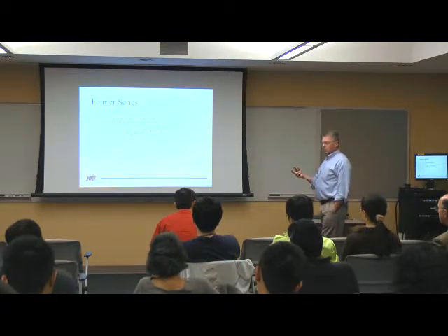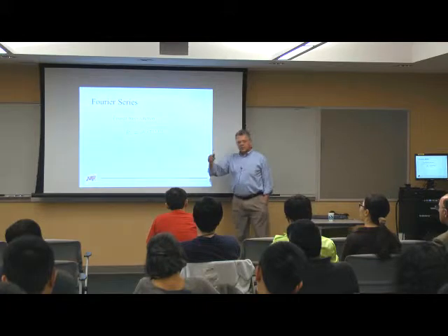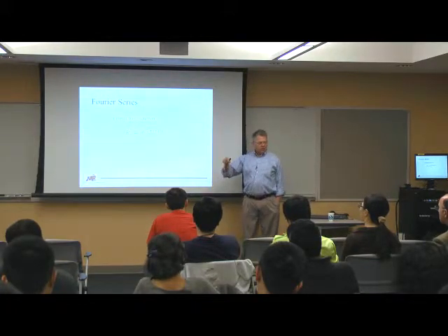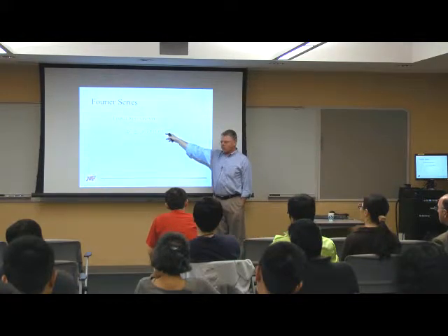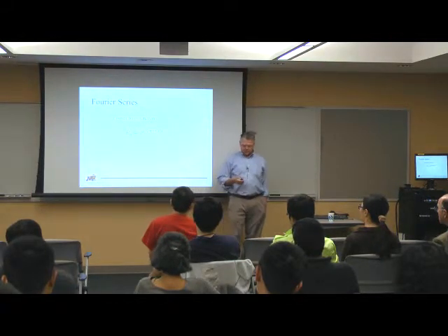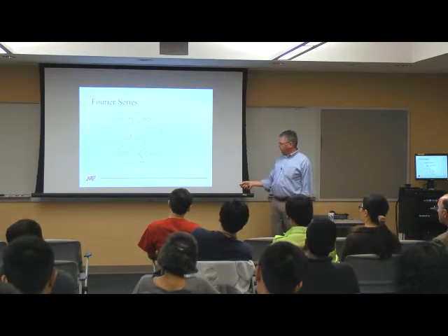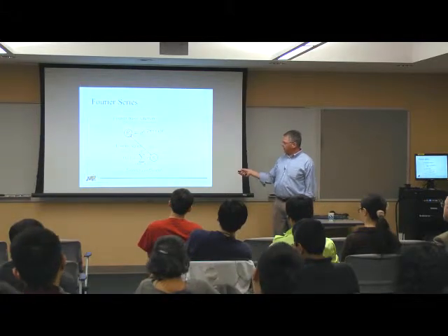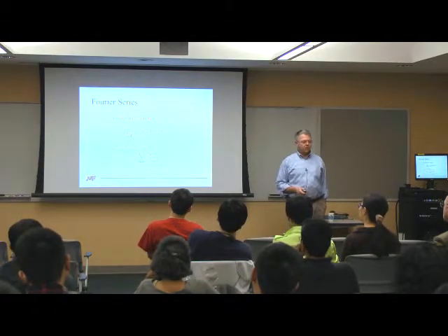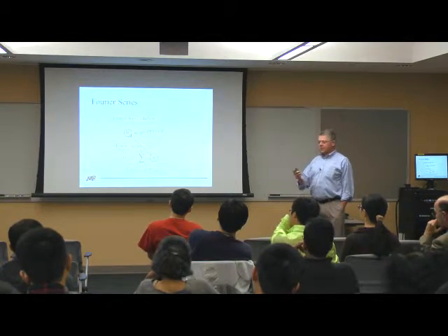All right. Take a sidestep here. Think about what you do with Fourier transforms. I have a time-varying signal, and I represent that as a linear combination of basis functions, sines and cosines, or this complex exponential. So you've all seen this before. I can take my function, represent it as a sum of these Fourier coefficients and this basis function here. This basis function works very well if I have periodic signals.